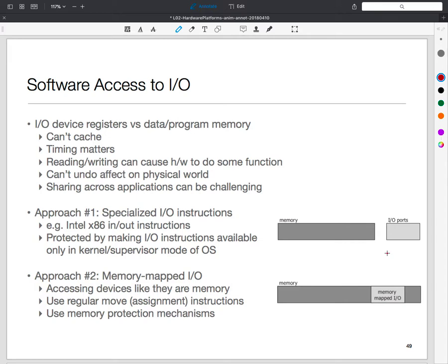It's just that we set aside some part of the address space for this purpose, and that may often depend upon the operating system, board designer, and things like that. So accessing devices in the second case is just like accessing memory, which is nice and clean because I can use just the standard way of programming things. I don't have to worry about this additional set of instructions.